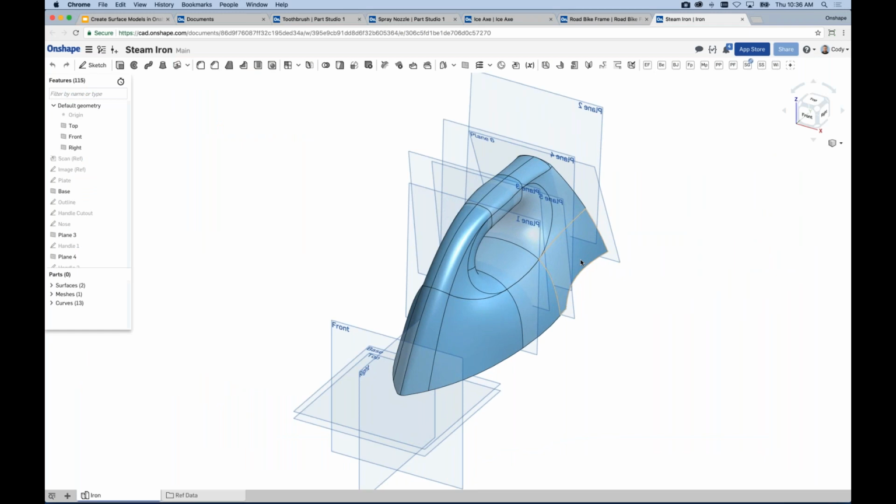Now, you can go back and forth, as I mentioned just a moment ago, a delete face. You could do a delete face, leave something open that will convert a solid into a surface, so you can go back to treating it like a surface model. So it's not written in stone once you go back and forth between the two. But generally, this is one of the last steps that you're going to do after you've finished much of the surface modeling.